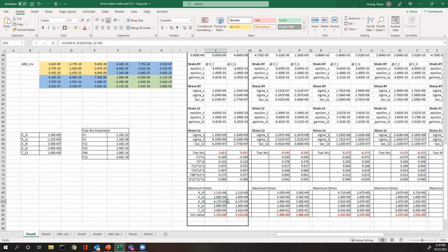There is a little bit of a trick here because it has to do with signs. For example, if the fiber direction is in tensile stress, I would use the if statement to check. If this number is tensile stress, the compression is not an issue. So I gave an arbitrary big number. That means it's not an issue. If this number is tension, then the compression threshold becomes a huge number. That means it's safe. Okay.